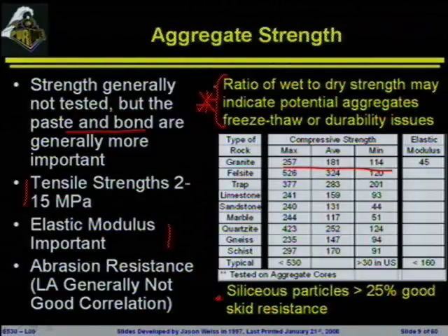Is this why the rocks in India have a compressive strength that's a lot lower? Their strength is lower. So a lot of times what you'll see is when they hit the limits on their high-strength concrete, they're fracturing the aggregates. And once you start fracturing the rock, there's very little that you can do to increase the overall strength. I mean, you can still get there by increasing the paste, but it's really sort of a law of diminishing returns. Other places, if you go to Seattle, they have fantastic rocks.